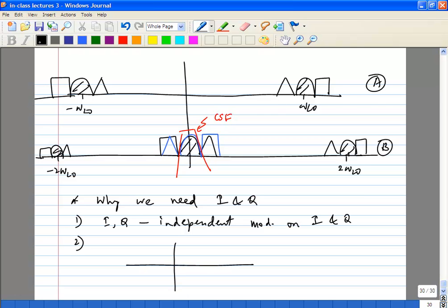If you look at the modulation, it's called quadrature amplitude modulation. So it looks like this. Obviously these are best represented by an xy coordinate rather than r theta, right? So if the modulation is based on QAM or some such where it's easily represented using rectangular coordinates, you would use xi and xq, I and Q, whether it's the transmitter or the receiver. It's a different question how it's produced, but you would use it that way.